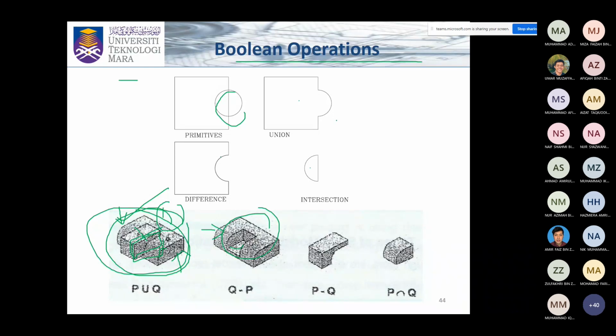Once you have that, there is an option called Boolean function in one of the drop-down toolbars. You can have addition, difference, intersection, and between each of these you can select which is your main body base. While I speak this, it's actually a lot clearer. Let me see whether I can show this video. Hang on.